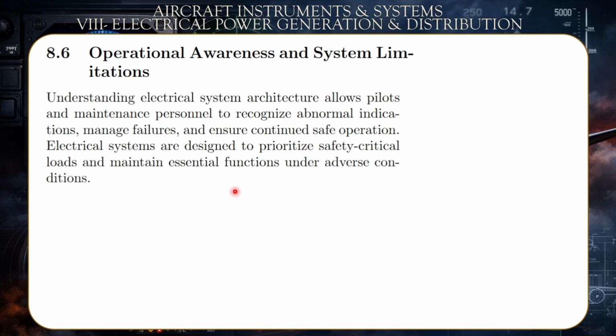If the main engine is no longer running properly, or if it flames out, then, if both engines flame out, you would need the deployment of the RAT, or ram air turbine, which goes below the aircraft, and it would generate less power than the main engine, which would require many of the non-essential instruments to be shut down in such a case.